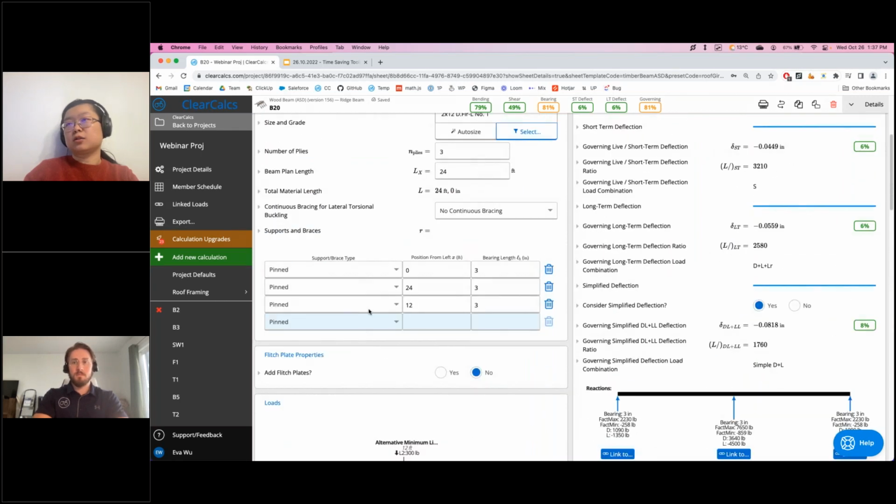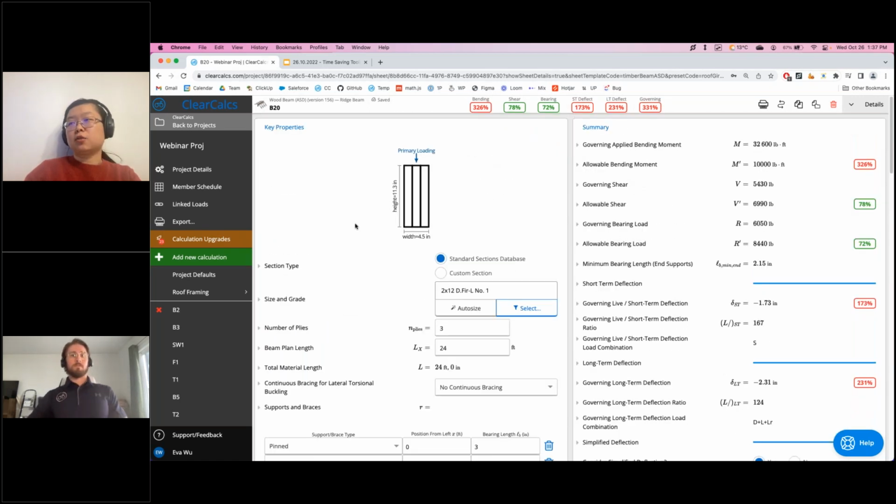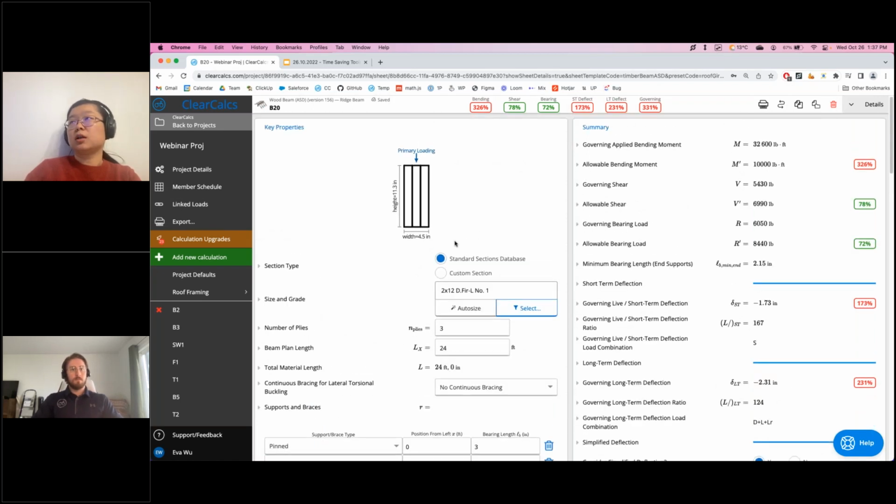And this has actually happened to me: the architect decided that a column in the middle is no longer acceptable, because they used to have a partition wall and now they don't. Now the client wants an open space and says we can't have this column in the middle. You knock out the column and the bending utilization is way overutilized. For this particular span now, we probably want a steel beam for more efficiency and to not exceed the depth.